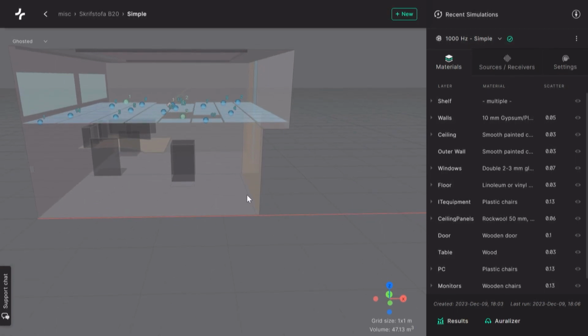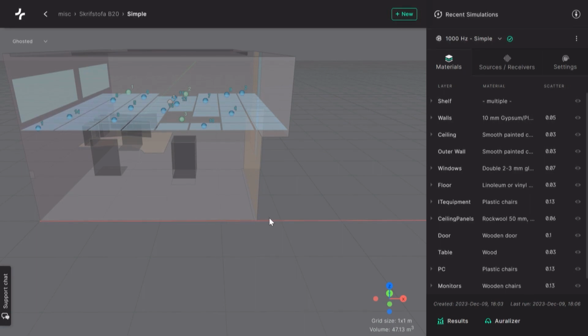but I found that making simplifications in the boundaries can lead to quite some errors. So I would suggest that you always put yourself in the frame of mind of what wavelengths you're dealing with. Think about the quarter wavelength, think about what will affect the wave, especially when it comes to the boundary, if the boundary is rigid or non-rigid, and really try to create an accurate skeleton of the room itself in order to get a good simulation result in the end. So I think I'll leave it at that, and hopefully we'll get some interesting discussion after this. Thank you very much.